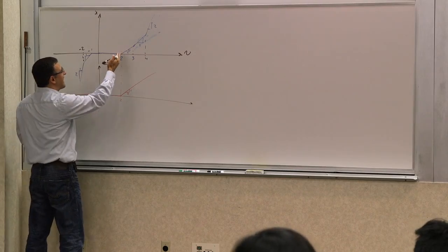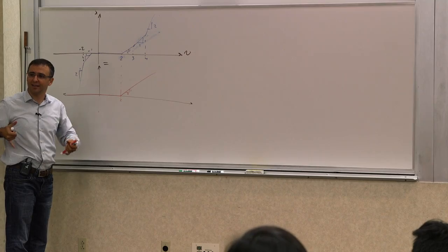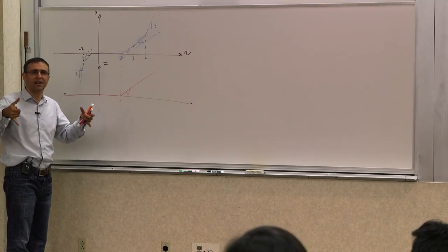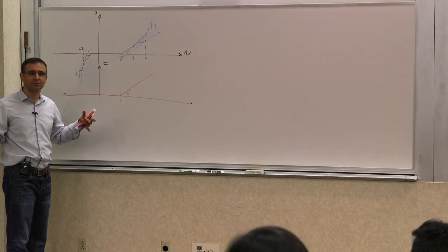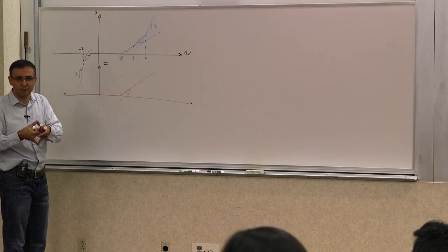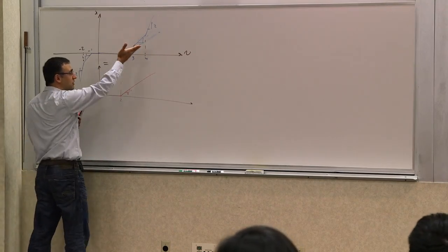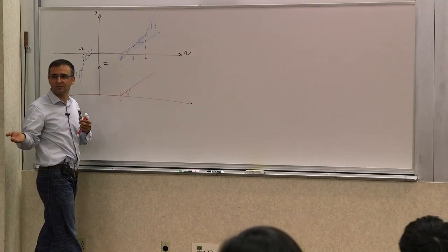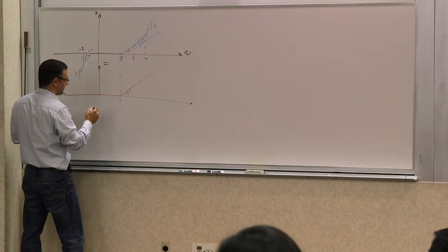So I want to make this as a sum of all these things, because if I make this as sum of these things, these being currents, I can get the sum of currents how? If I have current sources or the branches with different currents that I want to add, what do I do to them? Put them in parallel, right? If you put 2 branches in parallel, you add their currents. So if I create this as a sum of a bunch of curves that I know how to generate, I can create those branches and get that result. So what is the next thing I need to add to this to get to the next level?